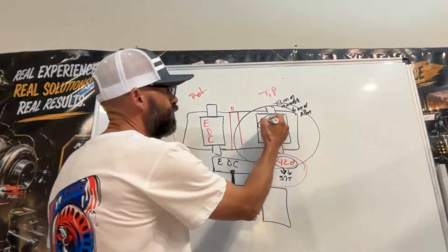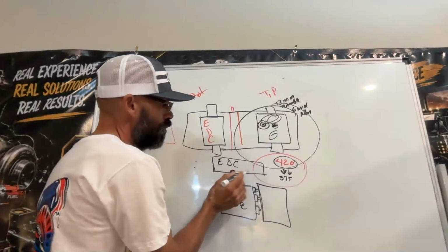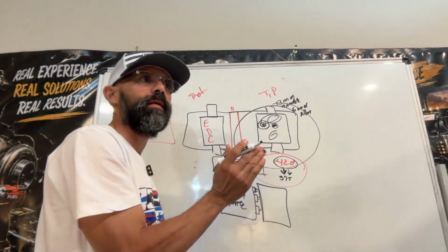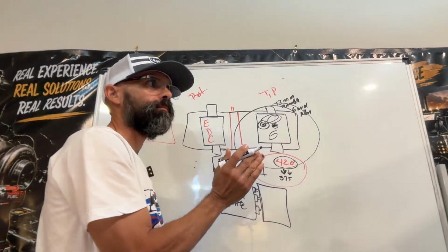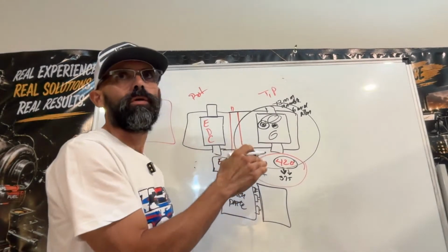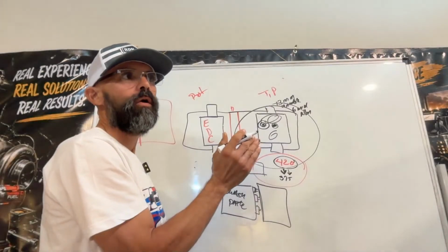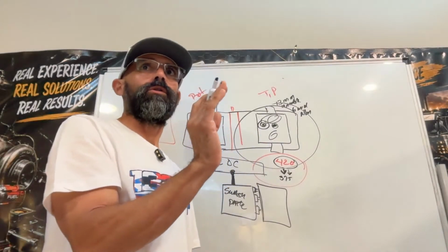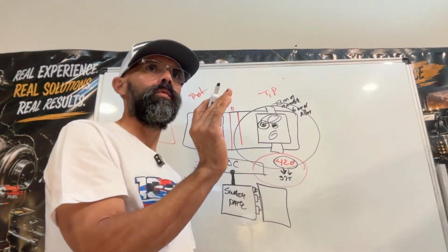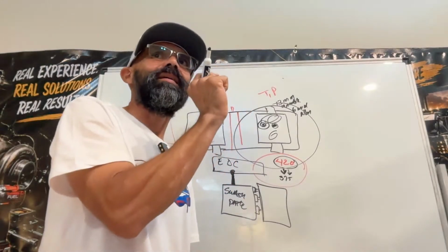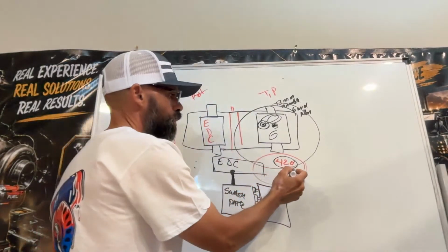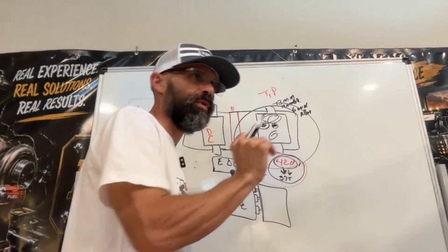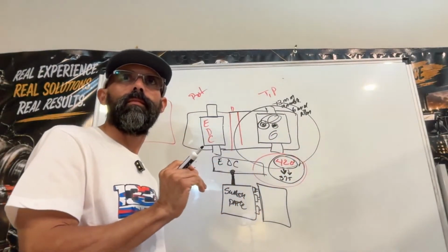So when you loosen this, you're moving the swash plate. Maybe your swash plate was inclining. It will stroke basically out of neutral a little bit. It's not gonna reflect on the thrust and pullback. Maybe your carriage is not moving by itself, but it's enough to throw off your charge pressure, to increase it.